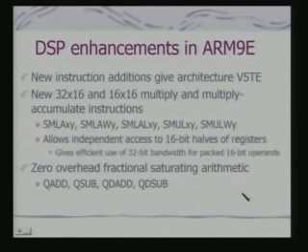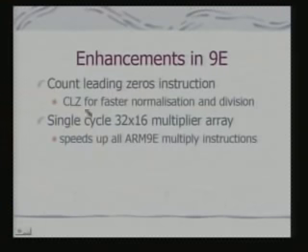Now 9E is a DSP enhancement. We had already discussed instruction sets, and architecturally you will find that what is being changed is your ISA, the instruction set architecture. It effectively means that there are enhancements in the ALU of the processor. So you have saturation arithmetic, and multiplication and accumulate operations. Let us see other things: interestingly, there is a CLZ, count leading 0 instruction.